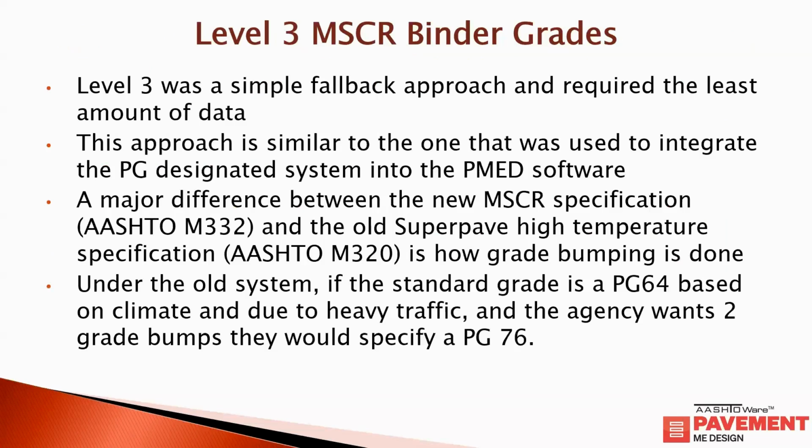Okay, so we implemented it in 2 levels. Level 3 was a simple fallback approach and records the least amount of data. This approach is similar to the one that is already used to integrate the performance grade (PG) designated system into the PMED software. A major difference between the new MSCR spec, which is AASHTO M332, and the old SuperPave high temperature spec, that's AASHTO M320, is how grade bumping is typically done.